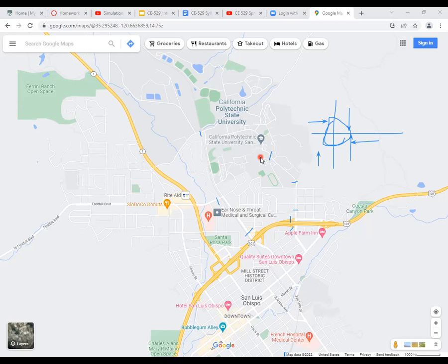The idea of calibration is that you model your system after the real world system. So you want to match your speed profile first. Going back to the question we asked, what type of data do you need? You also need that speed profile. You're going to need the traffic count data that you have to somehow convert into origin destination flows. And there are modern ways of doing that, by the way.